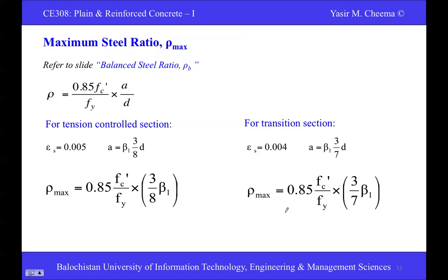One thing is called over reinforced. For over reinforced, we use the maximum value of rho, steel, we use more steel. For under reinforced, we use less steel. I will discuss why we use this one, and how we use it, in later slides.